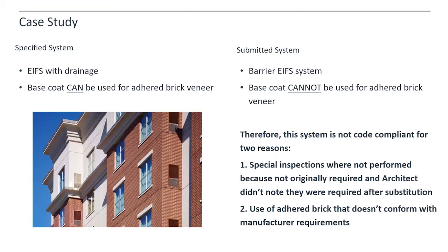But when you got into the product specifications, it was also noted by Parex that the base coat used in the submitted system cannot be used for adhered thin brick veneer. For two reasons, this system is not code compliant.